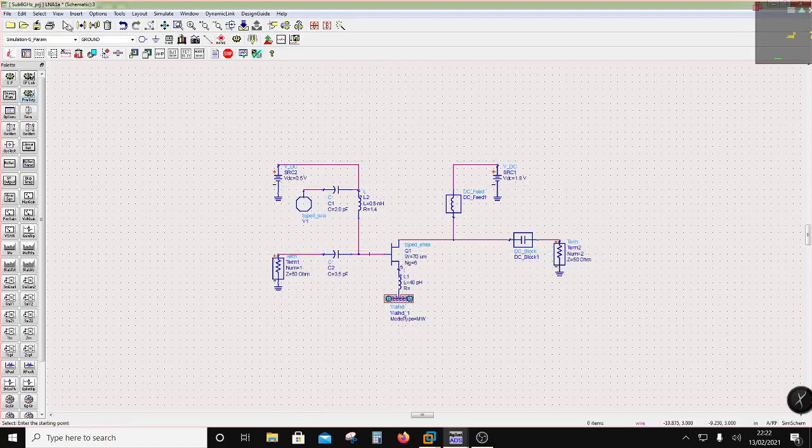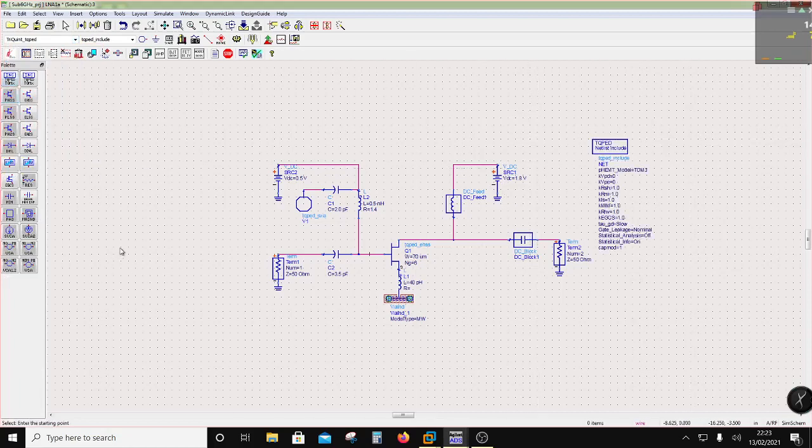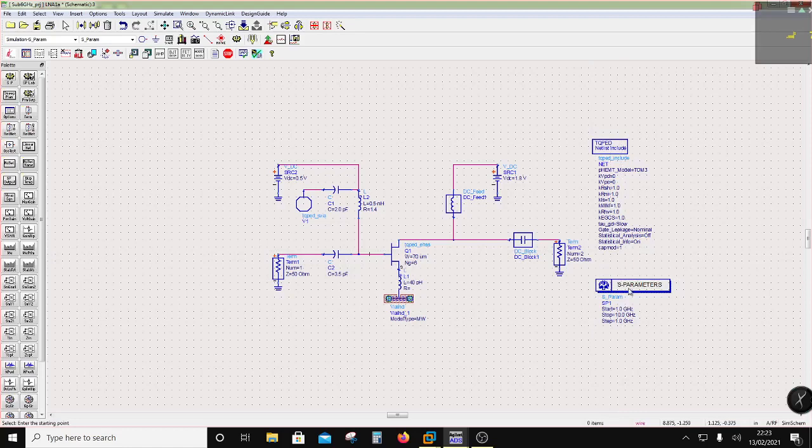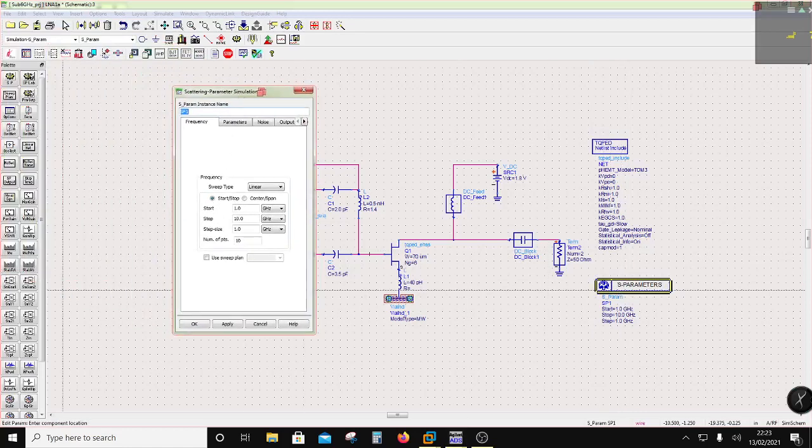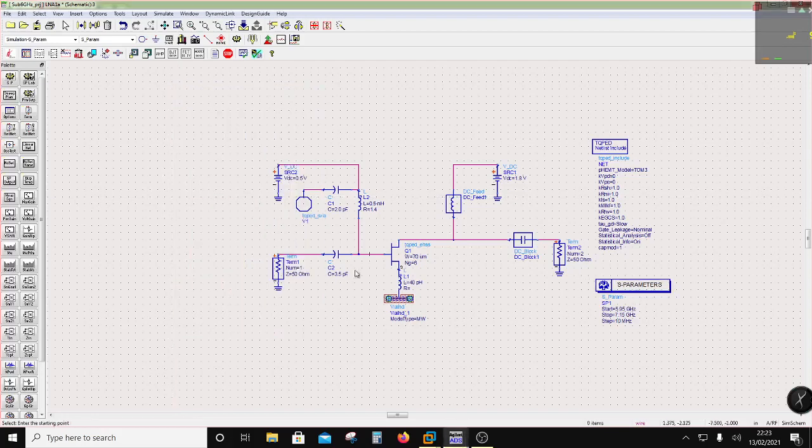Now we are going to look at the S parameters of this stage and also its stability circles and stuff like that. Let me get the include file here, and let me put here a simulation controller. With this simulation controller, I'm going to just work with in band right now. I'm going to worry about out of band later on because I have some idea about stability which I have implemented over here, so I'm not going to worry about that for now. I will go from 5.95 to 7.15, and 10 megahertz is my step size.